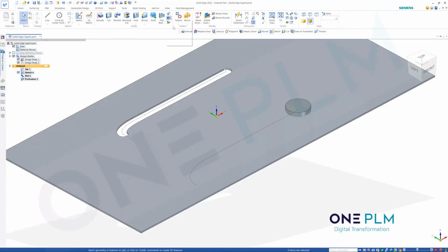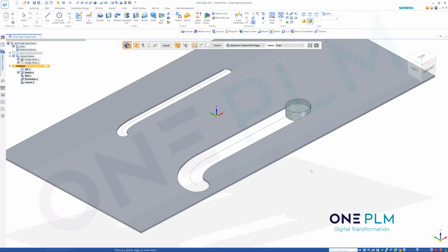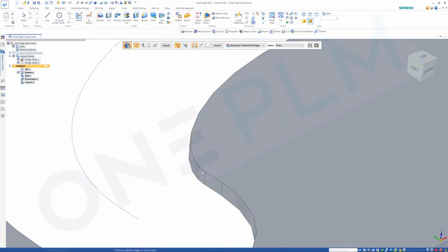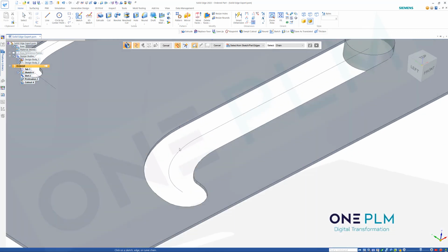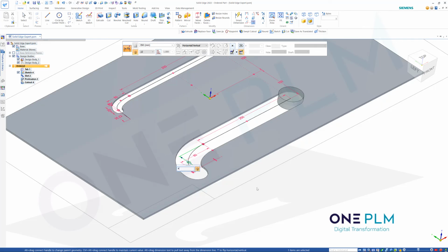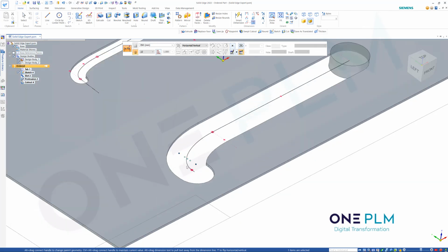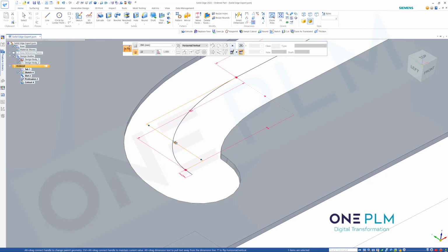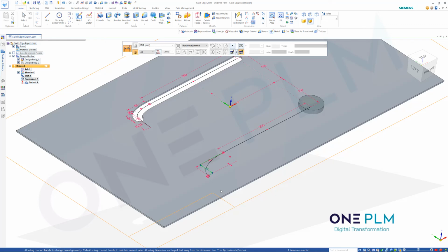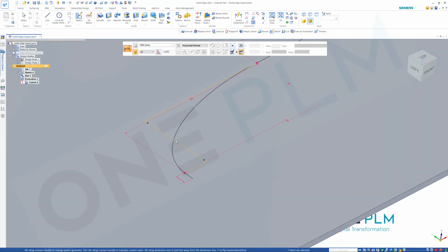So now if we do our solid sweep, make sure our sheet metal is active, choose our path, accept, choose our body, and then it's 3 accepts on there for that to work, and that's going to be okay. So what it was doing at this point where it's going progressive, it couldn't calculate because all the sizes were a little bit too small. So if we go to the sketch on there and change this size down, you'll see as we make these changes, we're starting to produce this sharp point. And once we get down to a certain version, it's obviously going to fail, but at that one point it managed to do something really strange on there.